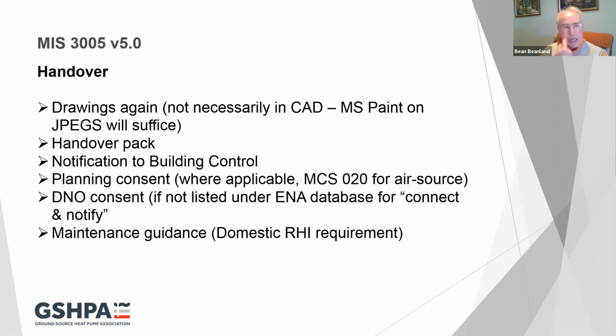Handover is another big issue. So I've said drawings again, not necessarily in CAD. It's really, really important that the drawings are in the handover pack. Again, it's something that you can point to. It's an audit trail, really essential. The handover pack, you know, there are specific requirements in 3005 of what should be included.